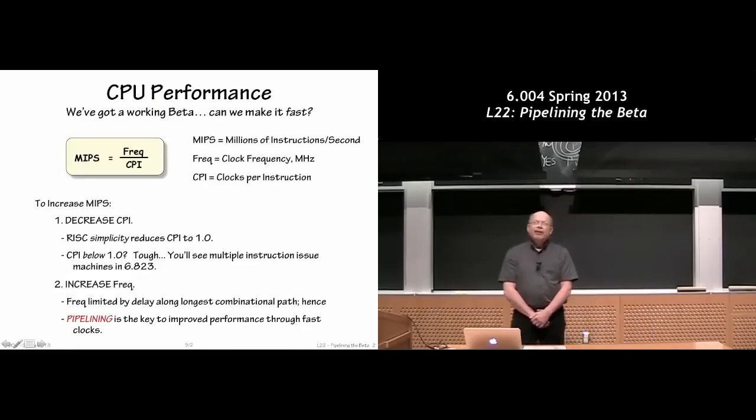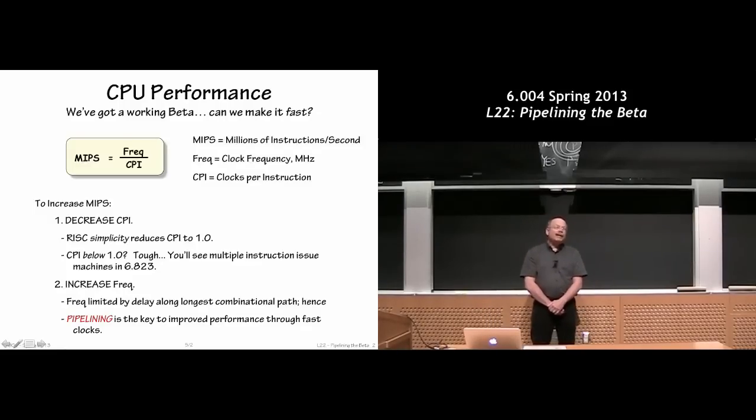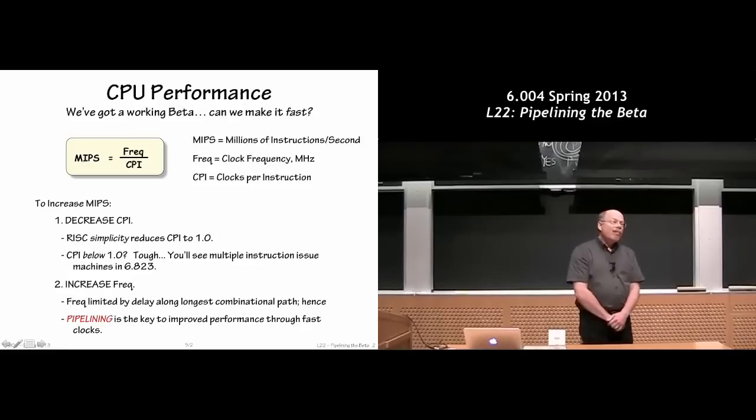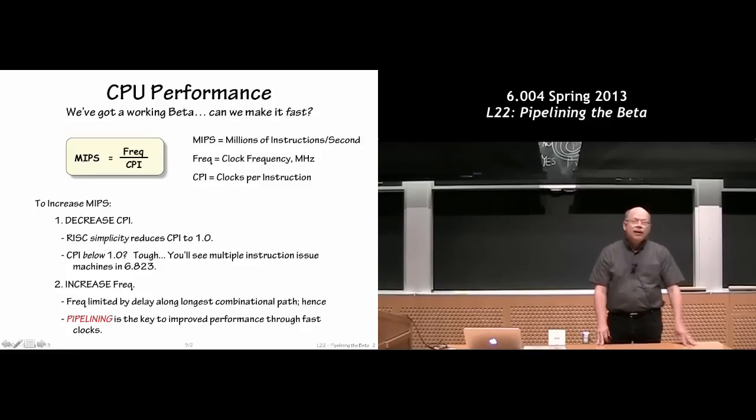And performance is measured in a fairly simple way. It's the number of instructions that complete each cycle, or how long it takes to complete an instruction. So mostly we don't care about latencies of how long a particular instruction takes to execute. We're much more interested in the throughput of the processor, which is measured over some span of time. On the average, how many instructions will it execute per unit time.